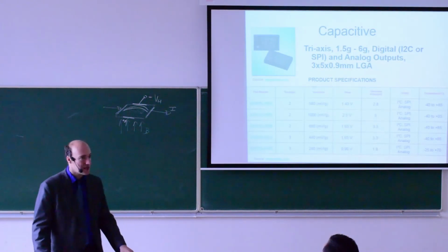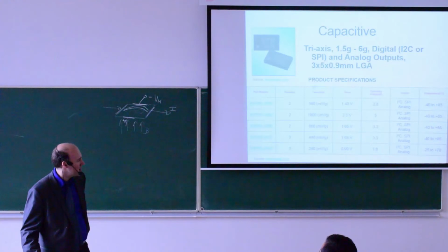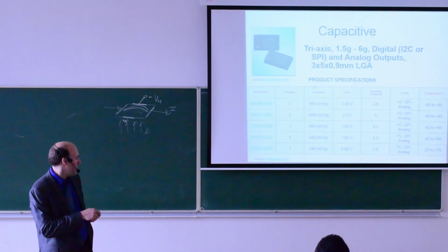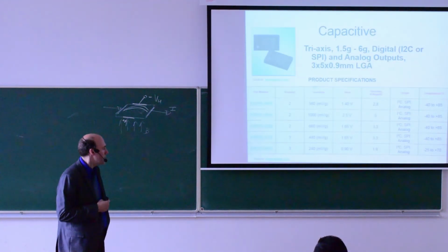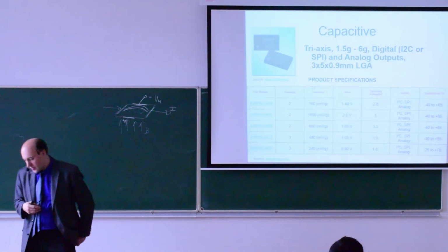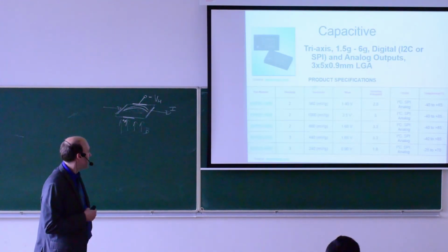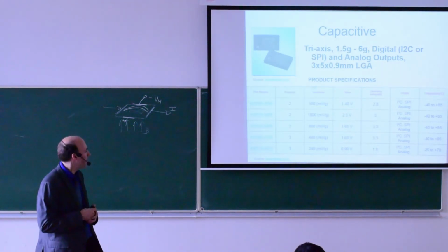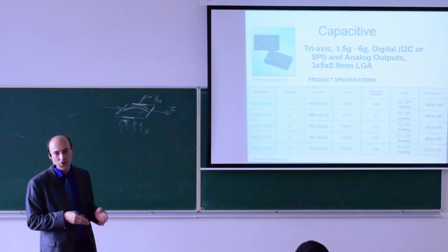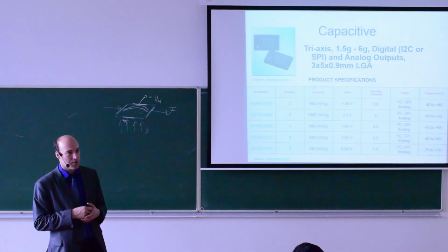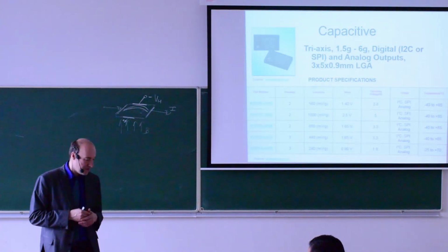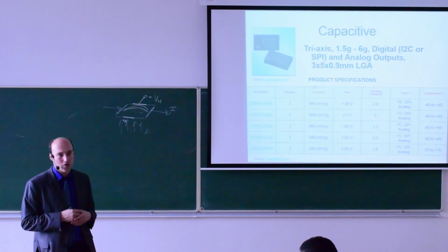I2C is a 2-wire bus. One wire is data, one wire is clock. SPI is a 3-wire bus, which is faster, but you don't usually need it for accelerometers. So you read either the number or the analog voltage that corresponds to the output of the acceleration. The accelerometers can be obtained in different versions. The difference is in how many axes you have available. In some applications you need two, mostly you need three to orient yourself in space. Even the 3-axis accelerometers are quite cheap today. The cost is not that significant compared to the remaining electronic circuits.